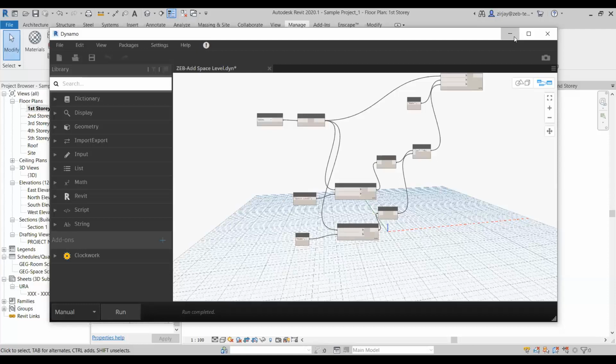Once you have done that step, we're ready to export our model to gbxml. So just go to a 3D view first. So everyone, okay, that step is already done. Okay, no questions. Okay, so go to the 3D view, go to File, Export, then gbxml. For this, we choose space volumes. Okay, export gbxml, use space volumes.